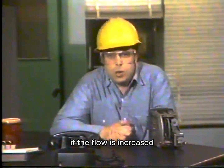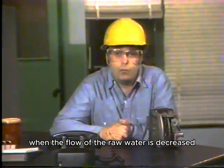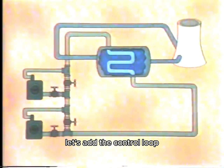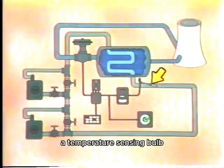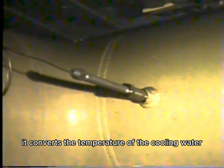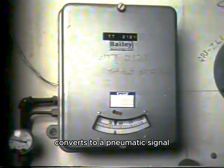If the flow is increased, the temperature of the cooling water will decrease. Conversely, the temperature of the cooling water will increase when the flow of the raw water is decreased. Let's add the control loop to our simplified illustration of the process. A temperature sensing bulb is used as the primary element in the control loop. It converts the temperature of the cooling water to a gas pressure, which the system's transmitter converts to a pneumatic signal.